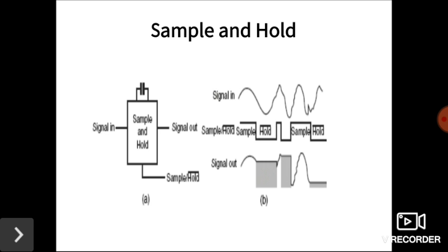Generally this is achieved by incorporating a sample and hold unit at the input, which during its hold state maintains the stability of the input signal through an external capacitor interfaced with it. That schematic diagram is shown in the figure, which accepts a digital input as the sample and hold signal. Hold is active low. Input and output waveforms for different states of the sample and hold signal are shown in the figure.